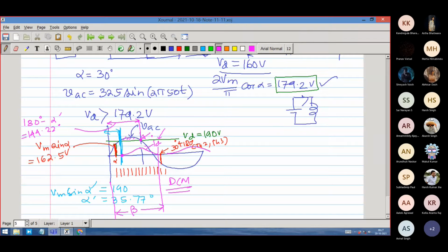Okay. Yeah, the V-rect is right. V-rect, let me do it in color, black. Let me do it in black. So V-rect will be what? You tell me. As long as the thyristor is conducting, TH1 and TH4, it will be just following the input voltage.